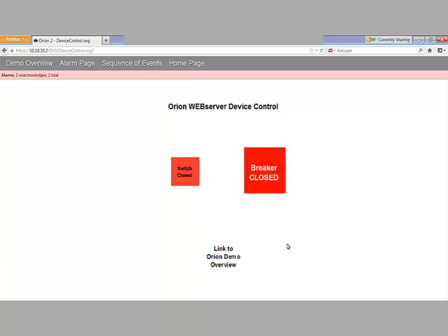And one optional feature that I don't have enabled here is some people like to show a graphical element on the screen when something's tagged. If you remember back here in the Inkscape drawing, we showed a do not operate tag and showed the letter T. You can designate what the tag symbol should look like. In this case, there's no tagging symbol that's used, but when you try to do control, you see that something's tagged.